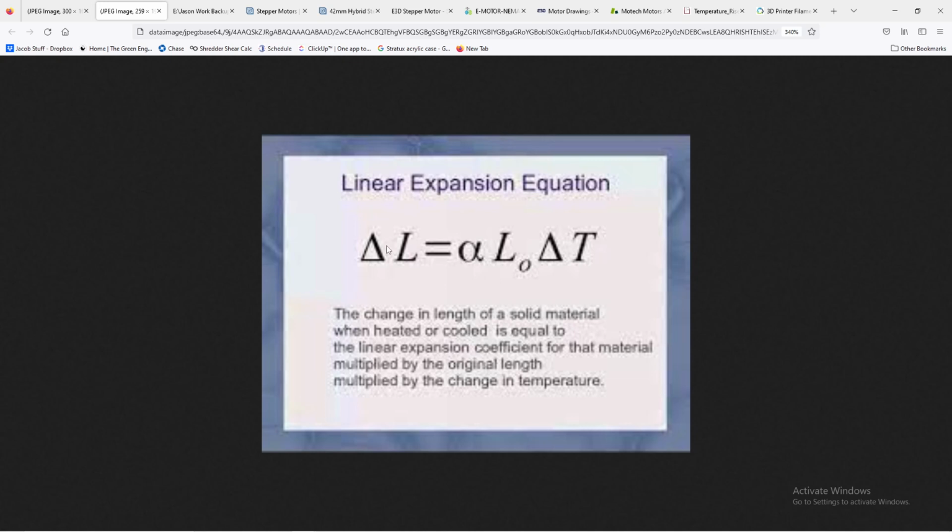So if you're printing at a lower temperature, after the part cools to your regular room temperature where you're using it, it depends on whether you're printing the part in 10 Celsius weather and then go into standard room temperature, let's say 25-30 Celsius, your dimensions are going to be off, right? Your dimensional stability will be off. So the closer you are to room temperature, the better you are. Or you could always calibrate that with scaling in the software. Anyway, that also has an effect.